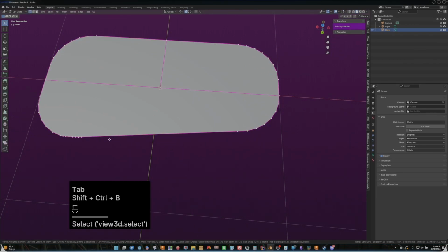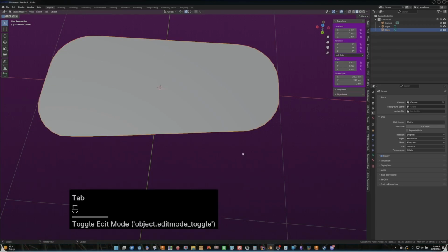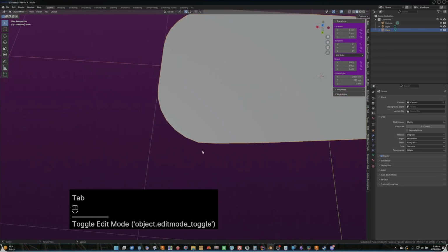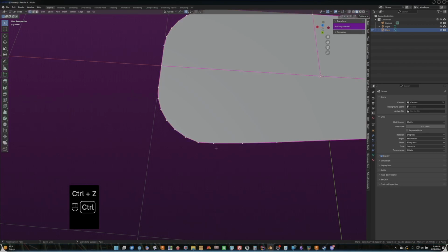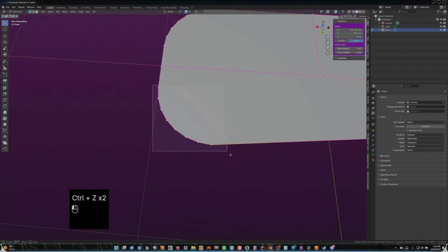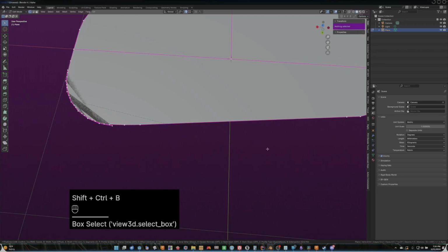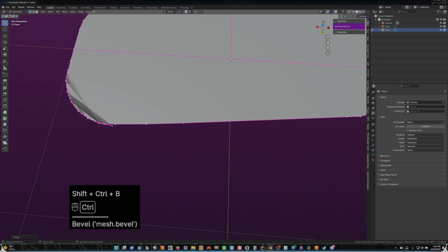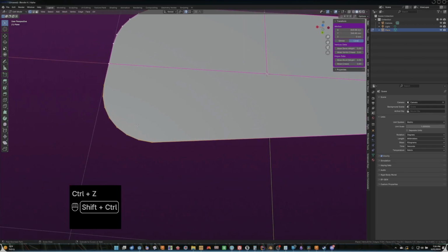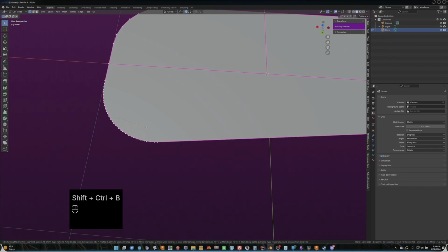And if we want it a little bit smoother, we can always bevel this out just a little bit more, stretch it. It doesn't taper so well. So instead of that, I can grab all of these, Control B, but then you run into issues. The reason you're running into these issues is because of overlap.